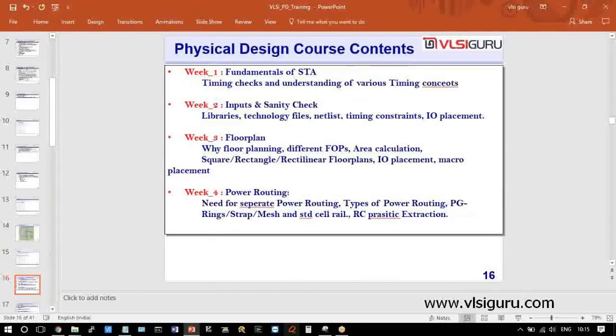But within ICC we will be doing the power structure. You get it, right? What it is? Will multiple designers do the IR? No, an IR team will be there, separate. Usually in companies, the IR people will give the IR structure to you, telling you to use this metal layer, use so many straps, use this width for the straps, and it should have so many decap cells, and all these things. We will be taking their protocol and implementing it as a physical design engineer. As I told you, some of you might get into the IR domain.